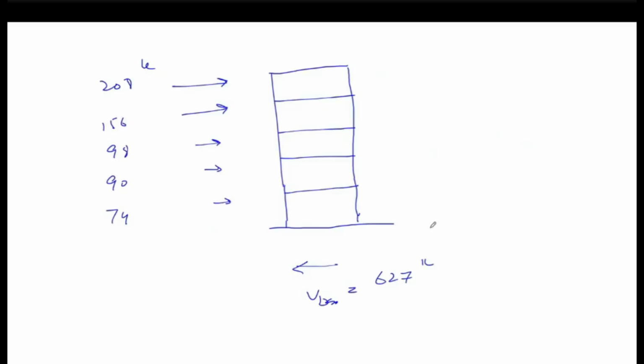So now this is the way you do the response spectrum analysis for the structural analysis and the design of the structure. Okay, and you can see that using this procedure can give you a discount of around 15% on the base shear. And one other advantage is that because it's dynamic and also in accordance with the actual mode shape of the structure, it is capable of taking into account the higher mode effects in the structure design.